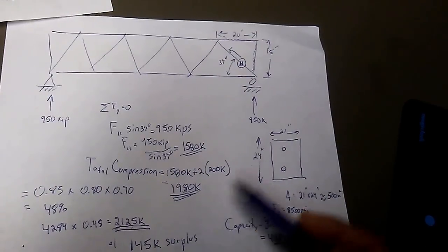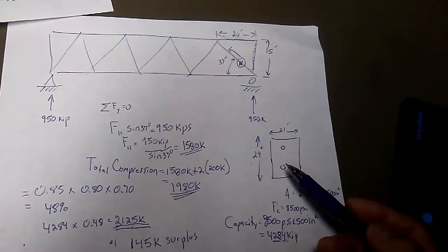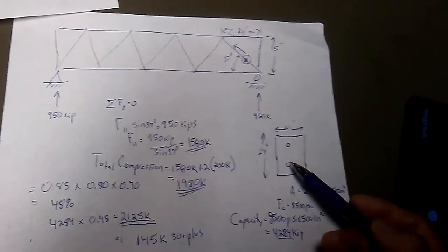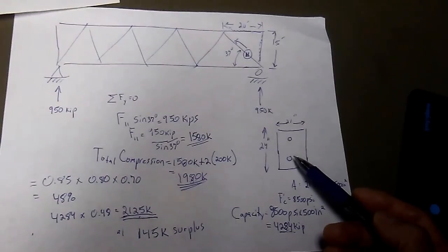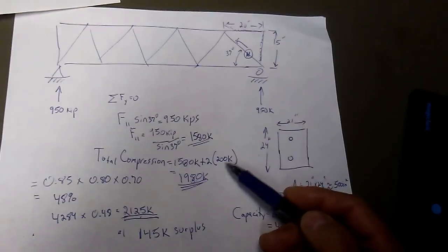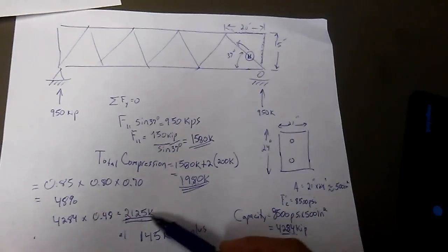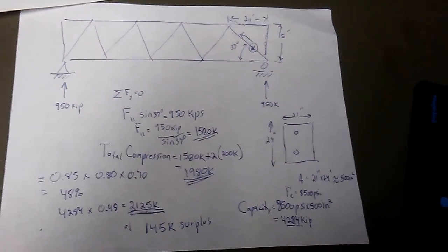All right, so as you can see, there's really not a lot of safety factor. There's not a lot of room for error in my post-tensioning. So if the contractor exceeded this 200 kips and he made it up to 350 kips on just one bar, he's exceeding the capacity of that member. And I think that's what may have happened.